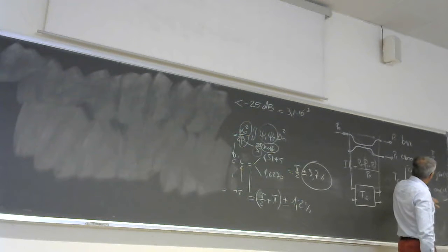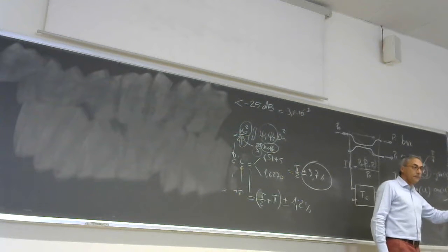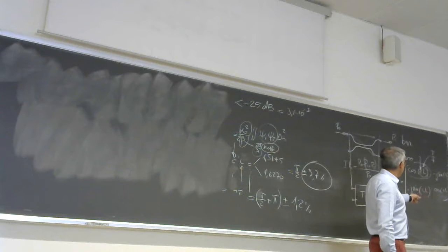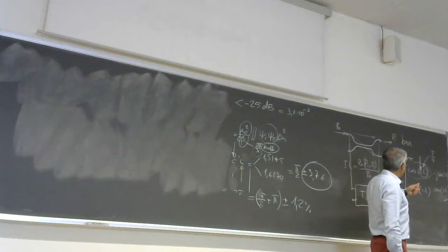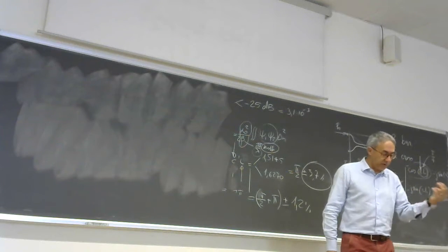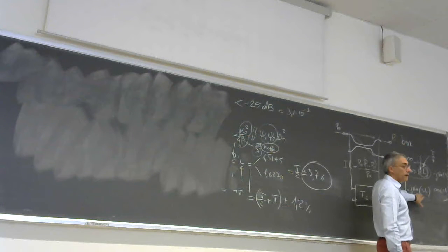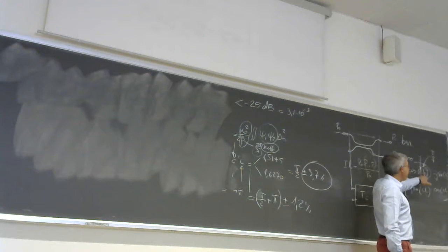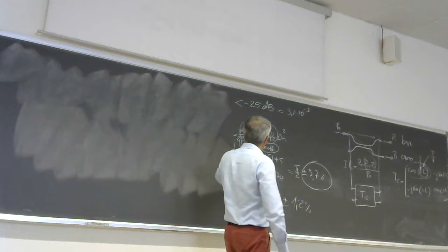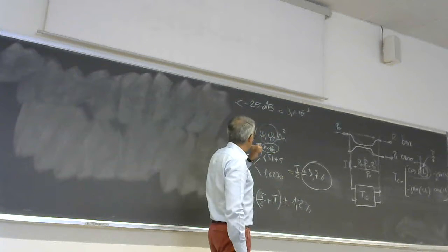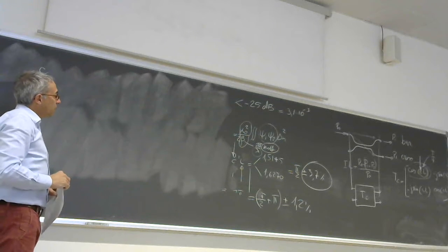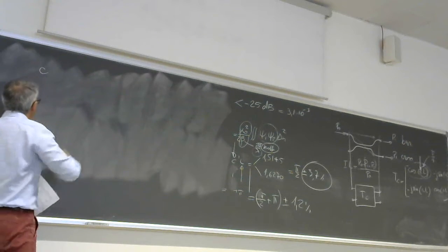This is the model of the directional coupler, a circuit model. But the physics is behind it: the geometrical dimension, the physical property, the refractive index, everything is inside. The electromagnetics is inside the model, hidden basically in this C. And the expression is what we found on Monday, this one. So the coupling coefficient C is not just a number, but is a function of the wavelength.